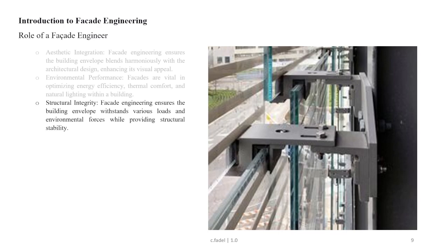Wind resistance. The facades are exposed to wind forces, which can exert significant pressure on the building envelope. The facade engineer incorporates wind load analysis and wind tunnel testing to assess the performance of the facade under different wind conditions. So the facade engineer should design the facade elements to resist wind pressure, mitigate wind-induced vibration, and prevent excessive deflections of the glass panel or any other elements that result in damage, and to ensure the facade's ability to withstand these forces, because it contributes to the overall structural stability and safety of the building.